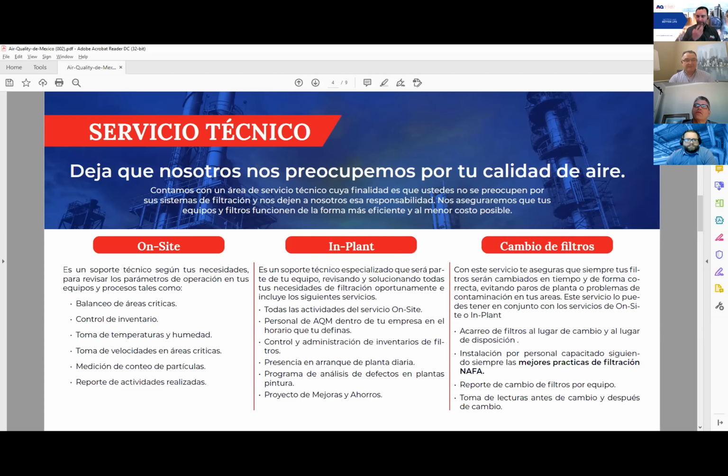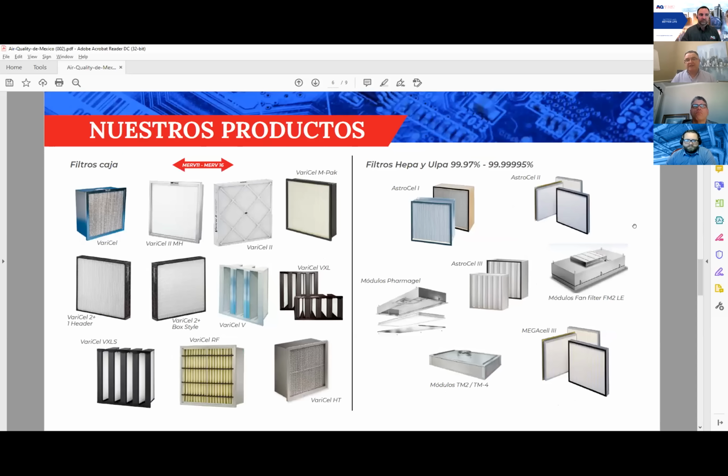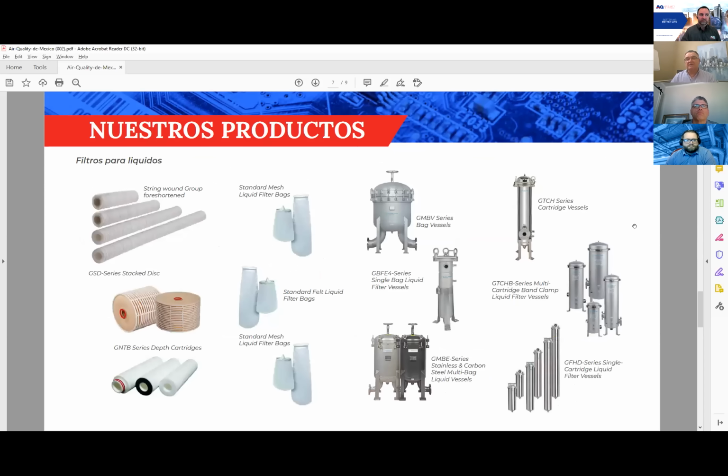The thing about the testing, as you saw in that tunnel, even if it's a PC pleat, what we would first do is a preliminary test. It is referred to as the face, or flat sheet test, to see how the paint behaves in the matrix of the expanded paper. And then when we qualify the media or the stack up that we feel is good, then we go to the PC pleat test. So the initial does not require a lot.